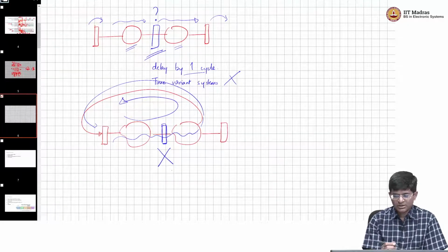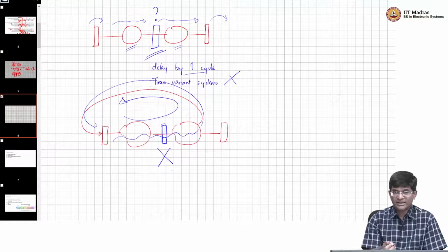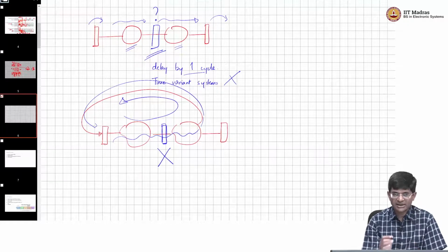So, this is basically where pipelining, as I have shown over here, where we essentially just try to insert a new register or delay element, may break down. It is not always possible. You can't just take any combinational path and stick a register in there and say, okay, I'll reduce the critical path. There are many scenarios where that actually changes functionality and is not permitted.